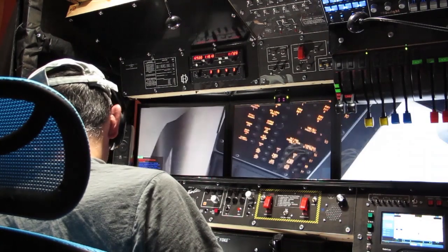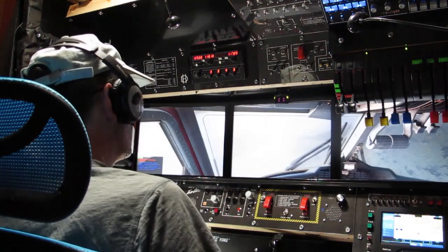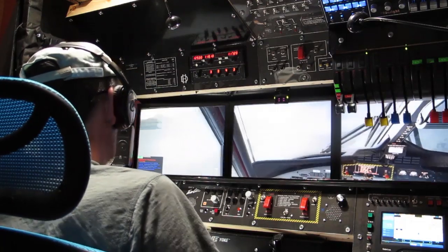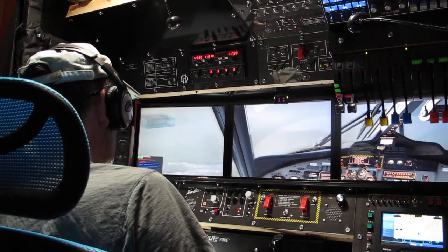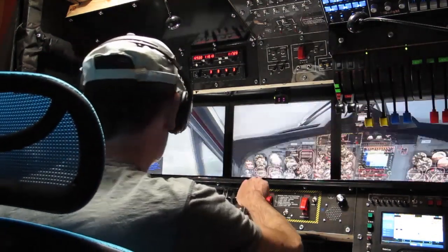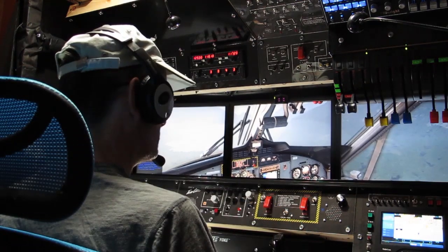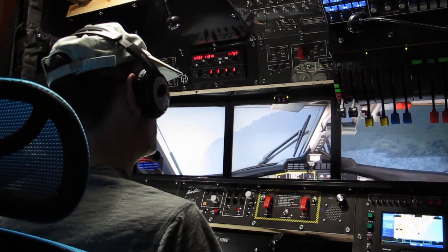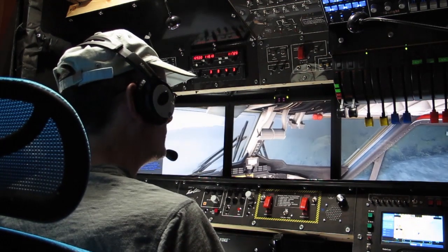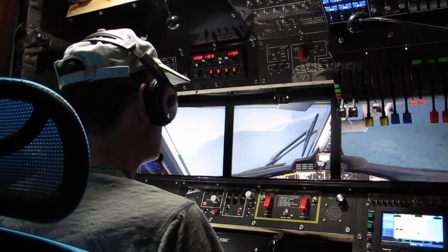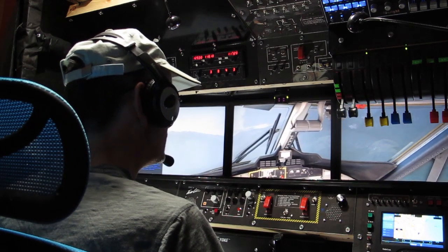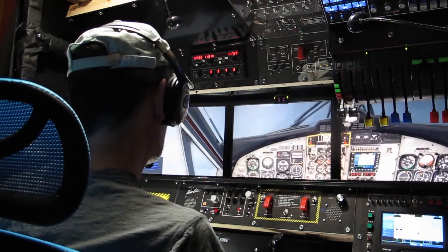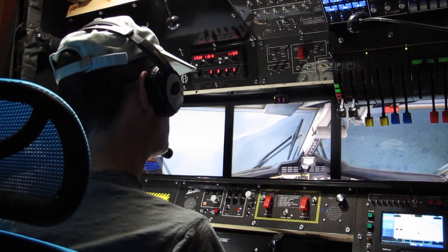So remember, the ground speed was 106, coming in the opposite direction. In this direction, where are we? So we've got 111. Comparing those two ground speeds, we've got 111 knots in one direction, 106 in the other, a 5 knot difference, and that means we've got a 5 knot crosswind from the left on the approach.